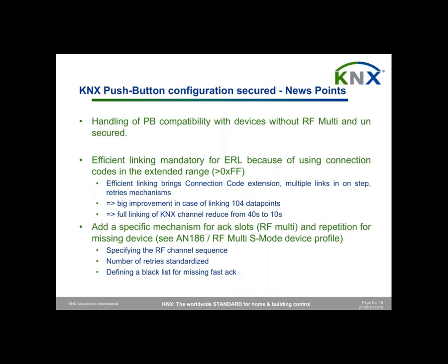The last part on the KNX stack Push-Button is about the configuration, secured configuration. One issue you must be aware of is that the new version of configuration is always compatible with old procedures. That means you have to embed also the old configuration procedure, which is not very different, but uses fewer services.